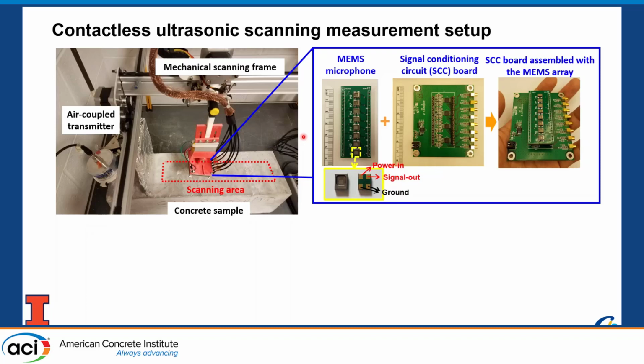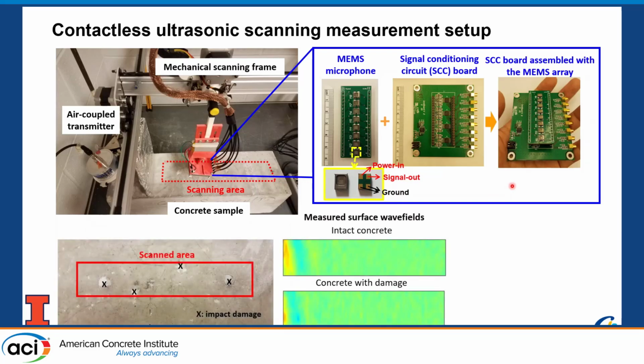Right. All right, and this is just some detail about our air-coupled receiver sensors. So just, again, to illustrate, here we'll do a scan over a concrete area. This is just a concrete surface, and we took a nail gun and just shot 4 places, so there's small localized cracking damage where the X's are. And here, we did it in the intact area and the scanned area. So here, this is actual data, so we can collect a lot of data and then reanimate it.